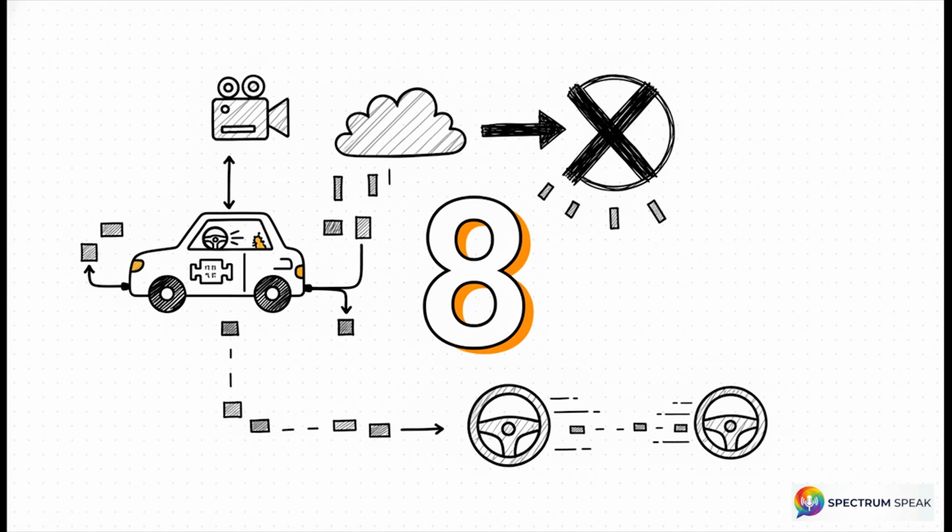Listen, you cannot use standard CAN to stream a high-definition backup camera feed or efficiently push massive over-the-air software updates. It's just not built for that. It is designed purely for short, highly reliable, lightning-fast control signals. Think a 4-byte message that says, steering wheel turned 15 degrees, or deploy airbags right now. If you try to shove massive amounts of data through CAN, you will completely choke your network. Always, always remember that 8-byte limit when scoping out your projects.